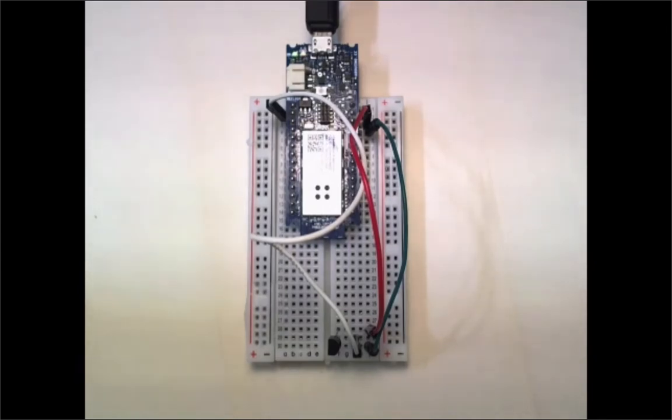So this will give me the temperature in degrees centigrade. If you are used to Fahrenheit, there's a simple formula to make that conversion. So what you can see here in what we call the serial monitor, I'm reading 246, that in millivolts is 738, and then applying the formula, this means I am reading 23.85 degrees. So this piece of code is telling us that the Arduino, in this case, is working.